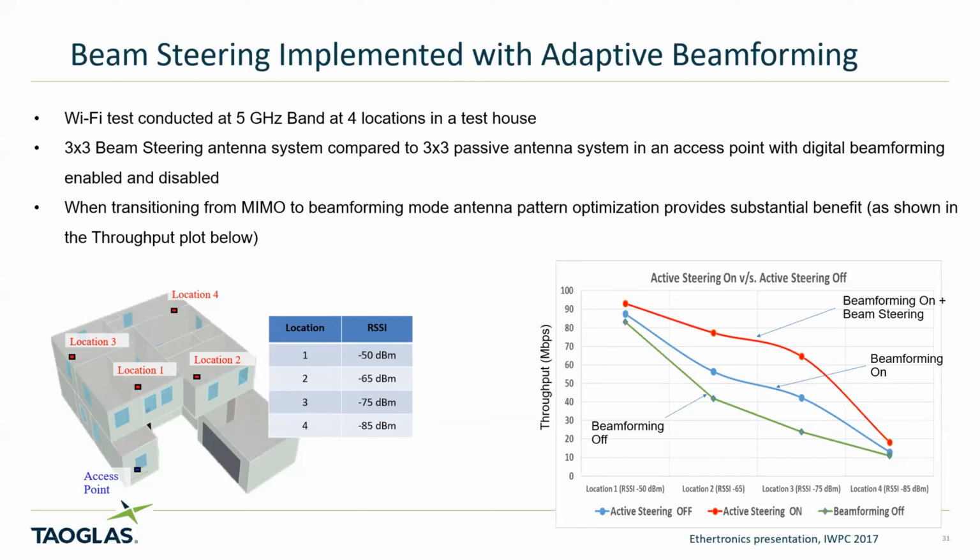Is that even necessary? Well, yeah, I'm pretty familiar with what's happening on the 5G sub 6 gigahertz node side. And typically what they're looking at now is a 32 to 64 element massive MIMO array for the node that would service the clients. But on that node, it's going to be dual linear components. It's not CP. I have not seen any CP requirement associated with 5G. If there is, I would like to see it and see what they're talking about. Everything I see is typically linearly polarized antennas, and on the node side, it's like you see on a 4G base station: slant 45, two cross polarized, linearly polarized elements in a MIMO configuration is what's being proposed and actually implemented on the 5G sub 6 gig node side.